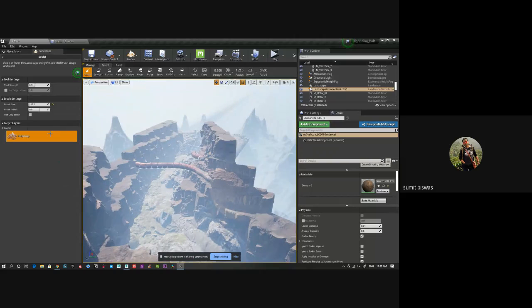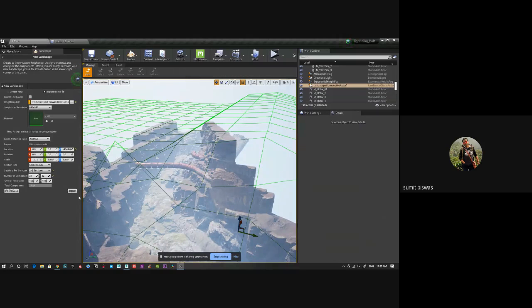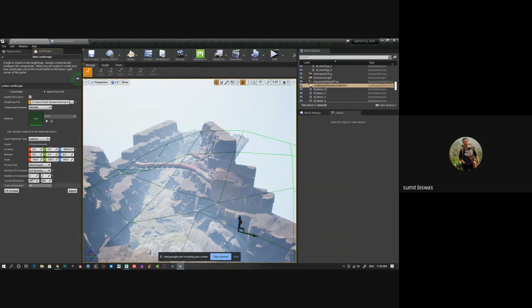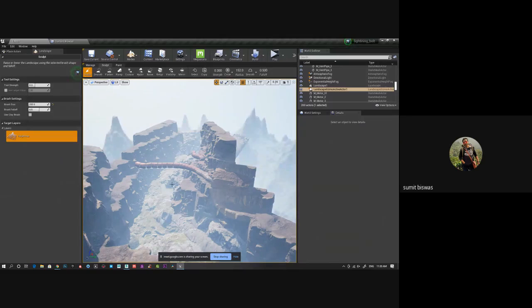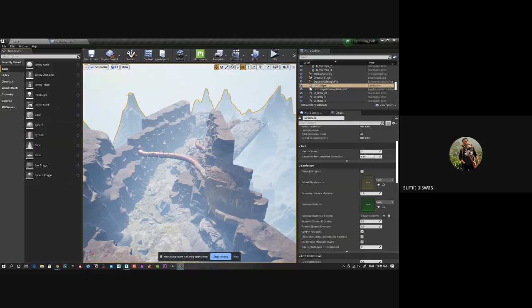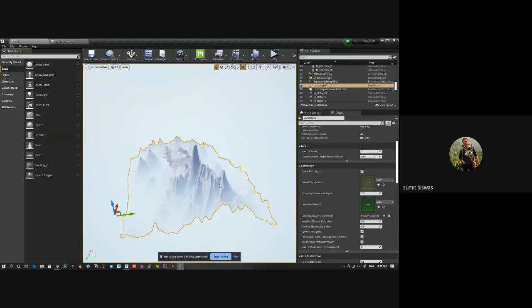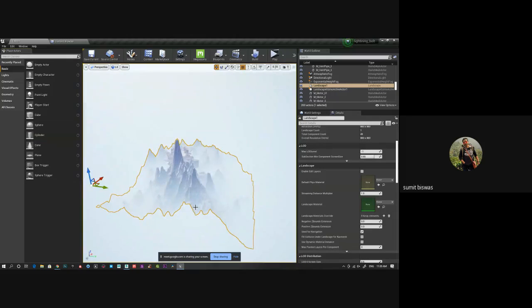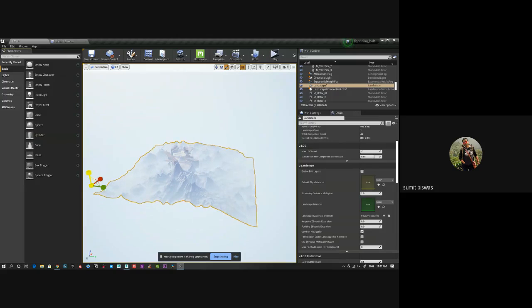So I'll undo this. I'll delete that and switch to data. This data is basically 7 by 7. So what I'll do, I just import this, create this entire mountain, and go back to my selection mode. Select this, F, zoom in, zoom out, and scale its height.